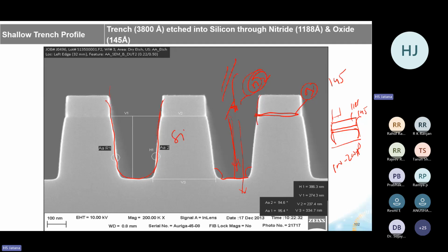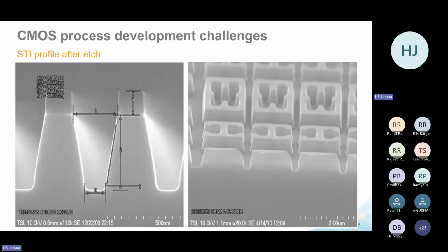And now you can deposit your high density dielectric oxide based on chemical vapor deposition, CVD, and CVD also has low pressure LPCVD, plasma enhanced CVD. There are the atmospheric pressure CVD. There are around 4 or 5 different CVD processes, and the process engineer has to choose some process and define it.